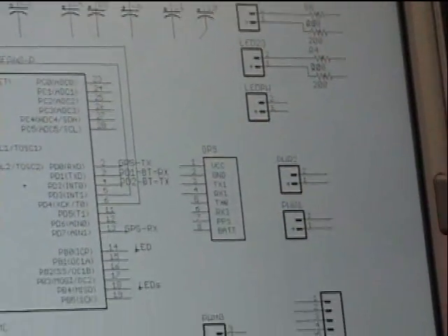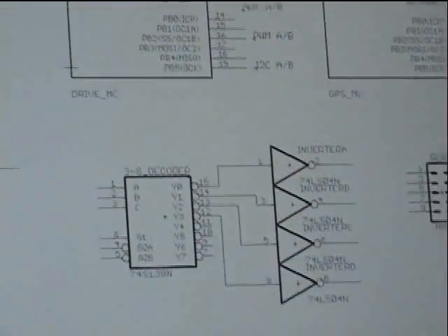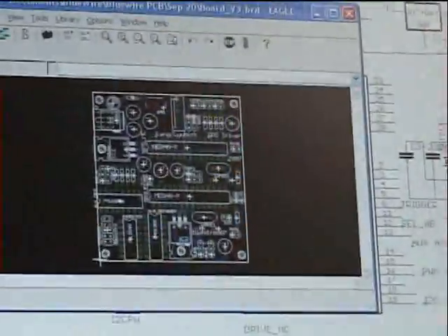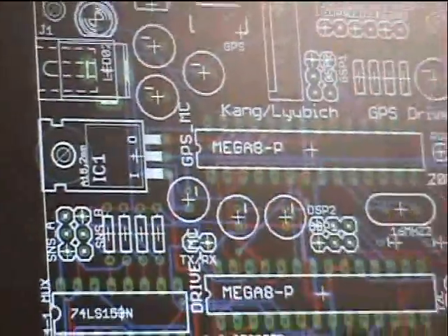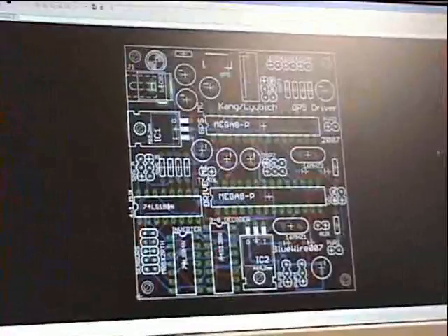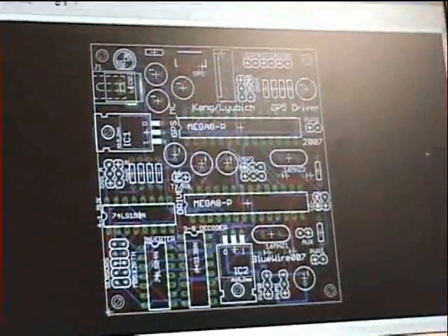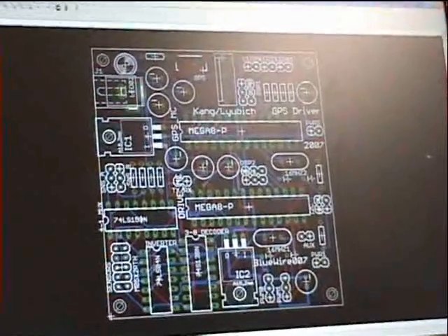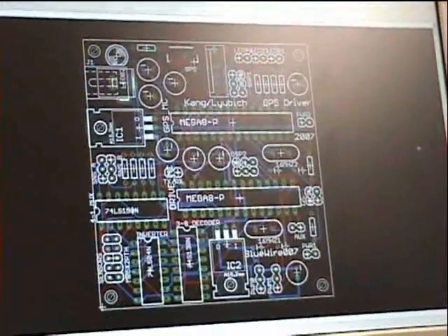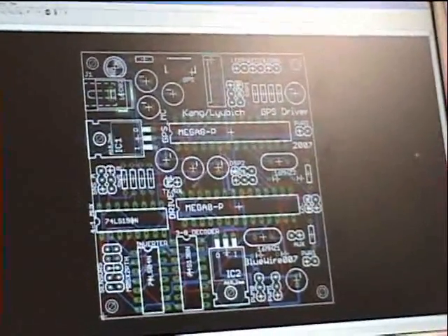And once everything is laid out, we switch the PCB to the PCB editor, and we place the components in, and we did auto route, which routed all the wires for us. And once this is ready, we ship this off to a company that creates the PCBs. And now we're gonna go over to see what is the exact process of getting a PCB.